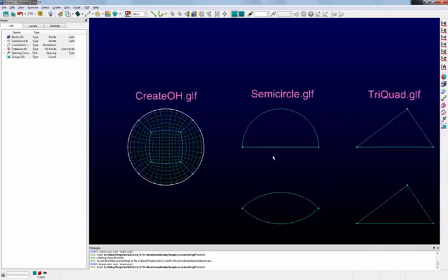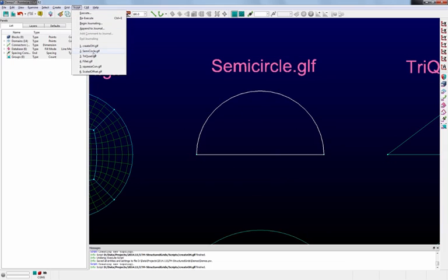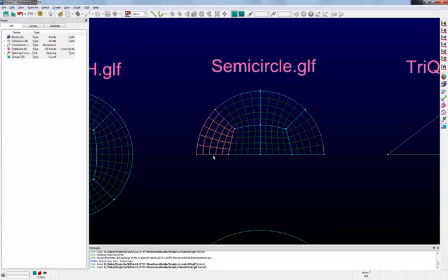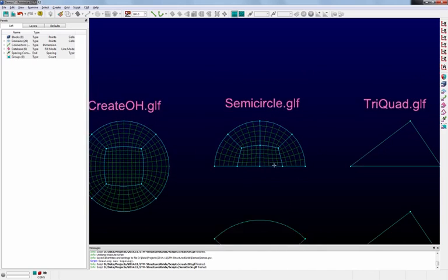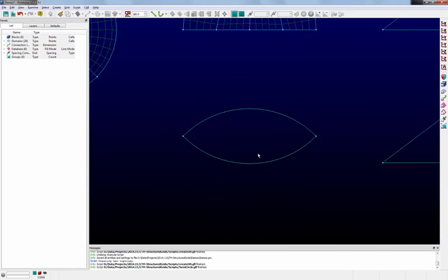Similarly, this sort of approach can also be extended to these half circle domains that consist of only 2 connectors. In much the same way, we're just going to highlight those connectors, go up to script and run the semicircle script. The semicircle script doesn't require an input because the dimension of this flat piece actually dictates what your radial dimension can be. So whenever you run this script, it automatically determines that, generates the topology for you, and voila, you have your topology within a matter of seconds.